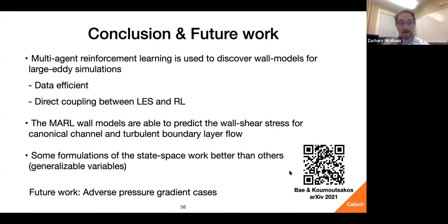I'll start off. I was interested in a lot of this. I've seen that some of your wall models use the universal law that has the matched asymptotic with the sticking condition on the wall and the log. I was curious how that relates to simple models that use stick-slip conditions, where they allow a boundary condition where the velocity slips against the wall.